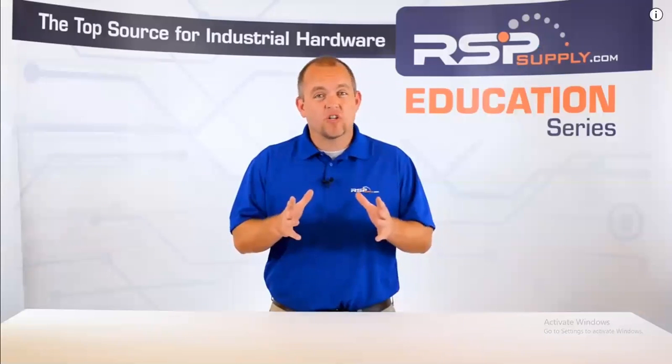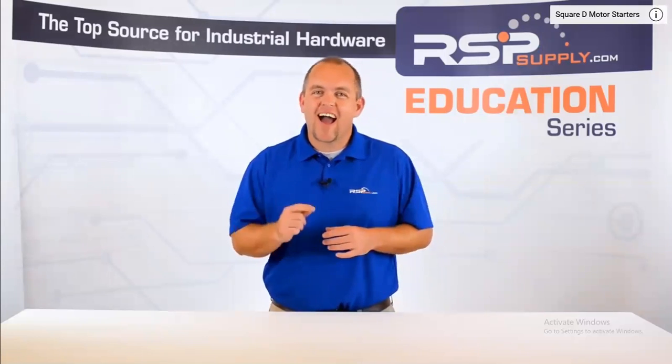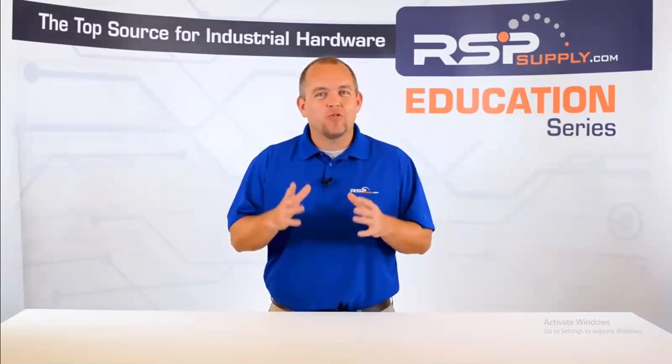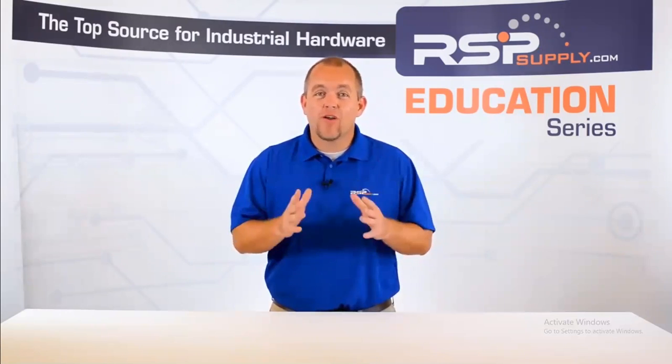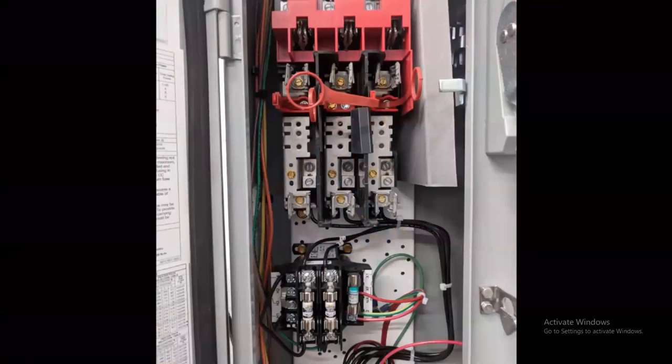In DC motors, the armature in the motor has very little resistance, and the high current levels that can occur from starting a motor without the use of a starter can damage the armature on the motor's very first use. So in the case of both AC and DC motors, especially higher voltage, more horsepower situations, the motor starter is critical.